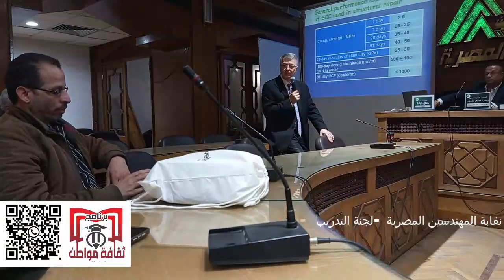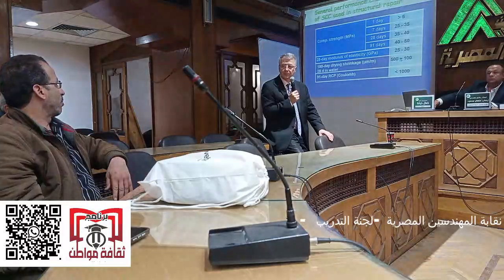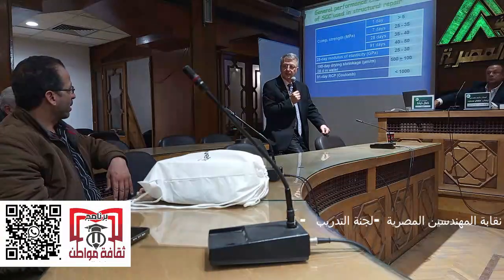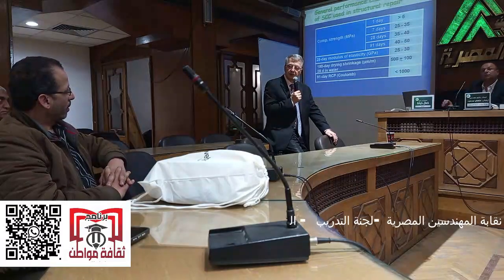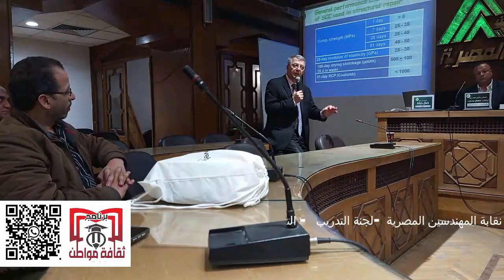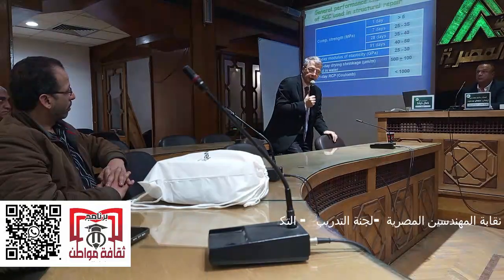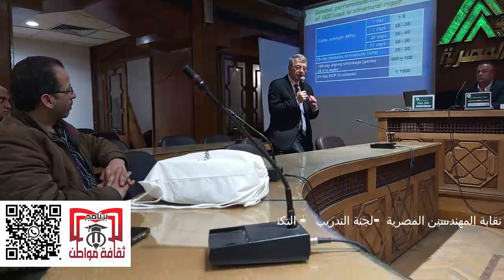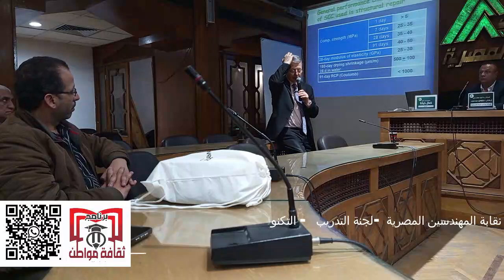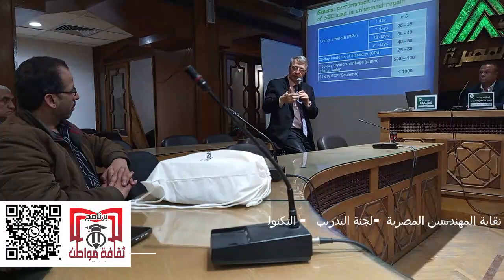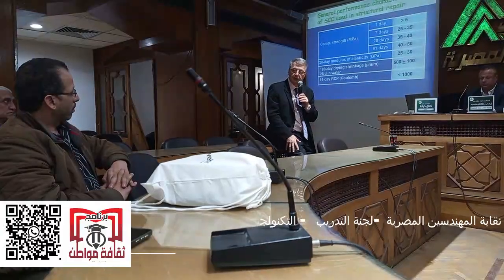In Kuwait, we use 5% microsilica plus 30% GGBS. Yeah, 5% silica fume, GGBS 30. That's a very nice combination. When you combine silica fume, low percentage, 5%, with 30% GGBS or 30% fly ash, you are getting good packing density of the powder. And you are reducing the space that needs to be filled with hydration products. So you get low porosity, high strength, high durability.